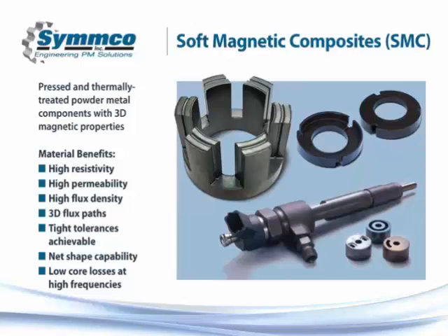Okay, and then what kind of surface finishes are you able to achieve? Good question. Just out of the press, if we aren't looking at any post-grinding processes, it's really easy to hold a 125 or slightly better. So that's just out of the press. That's an everyday occurrence. With machining, there are some parts that are very, very surface finish oriented, and getting to the 32s and below is really easy. Much lower than that if we do need a grinding operation to directly get the surface finish.